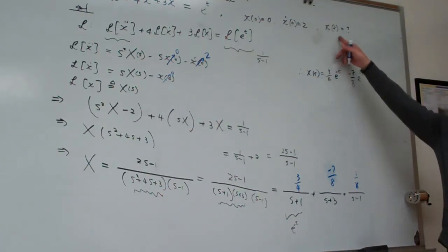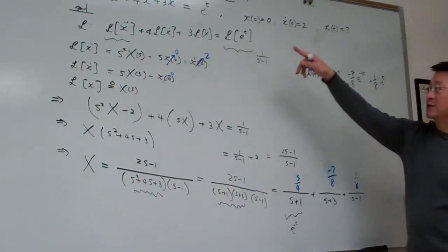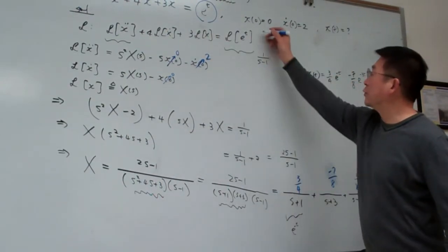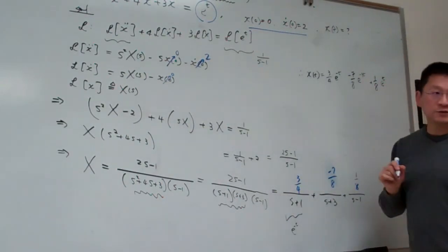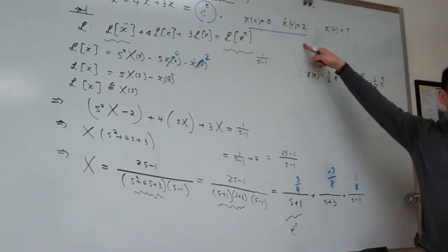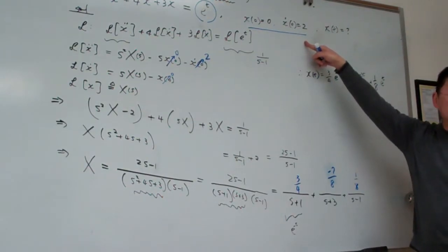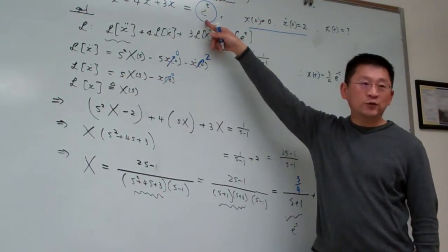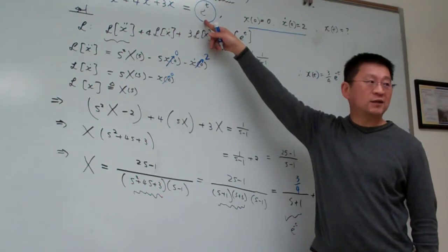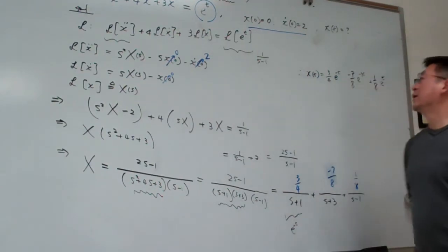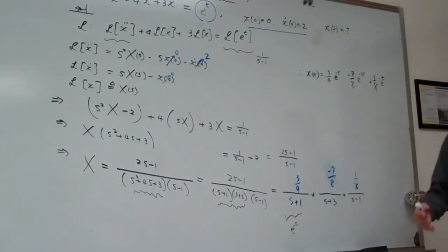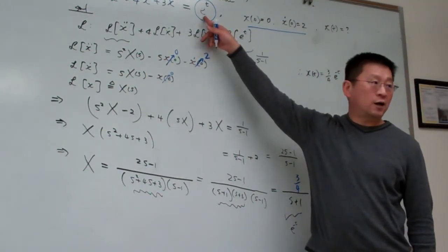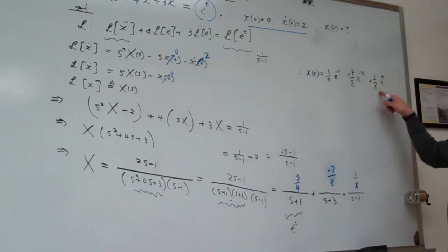This is the total response of the system, because the system is under the forced excitation and also under the initial conditions. Initial conditions contribute to transient solutions. The given force excitation contributes to what we call the steady state response. The steady state response always eventually will follow the pattern of the form of the given force. That is this term.